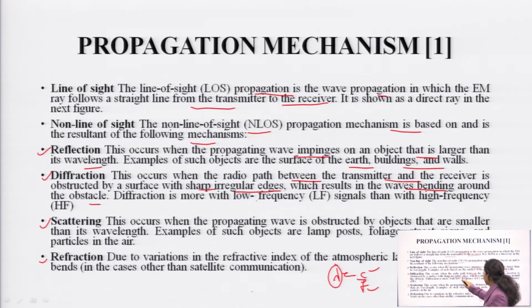Now, diffraction is more with low frequency signals than the high frequency signal. Why is it so? Because in case of low frequency signal, the lambda is quite high and it is going to affect the quality of the signal much more when it impinges on a sharp object.